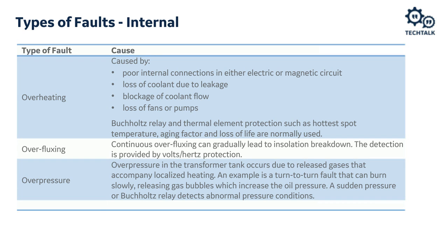Eventually, the winding fault would probably evolve, but depending on the initial severity, there could already be quite a pressure buildup. Our more advanced relays now have some pretty good turn-to-turn fault detection functions, but for general purposes, an external Buchholz relay or a sudden pressure relay would typically be used to detect pressure issues.